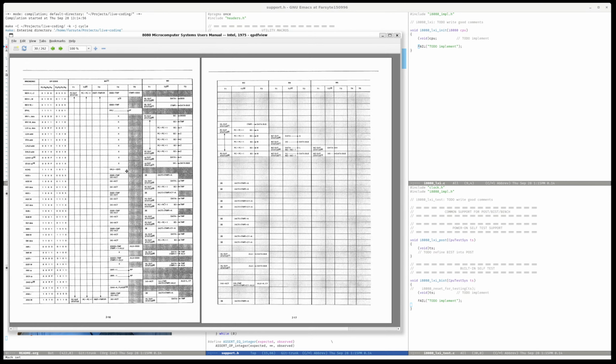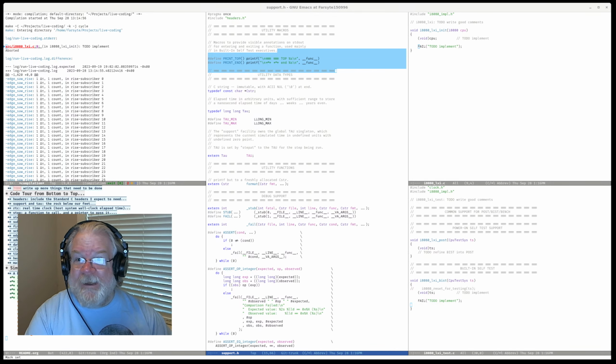It's similar to these other guys that have a two bops, that have an immediate. Let's use MVI as our comparison. So MVI here has a do nothing T4 and does this. So we are just like MVI, except we are going to be doing 2 bytes into 2 registers. So LXI is MVI on steroids.